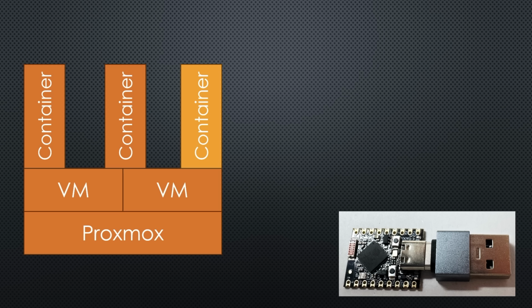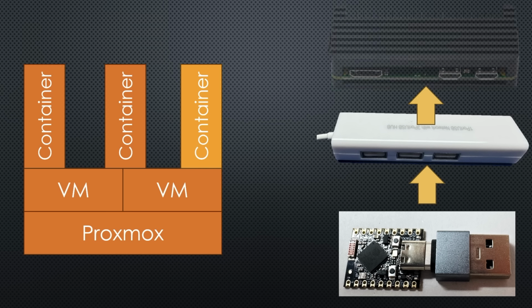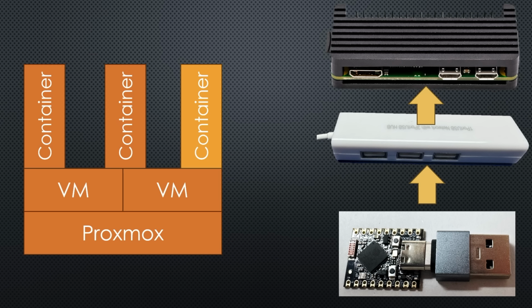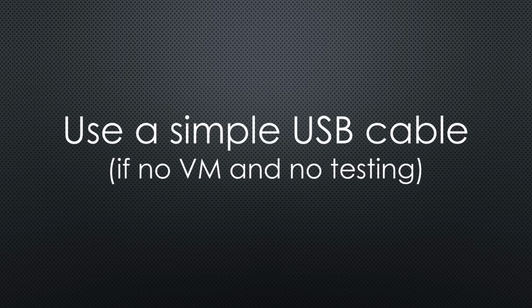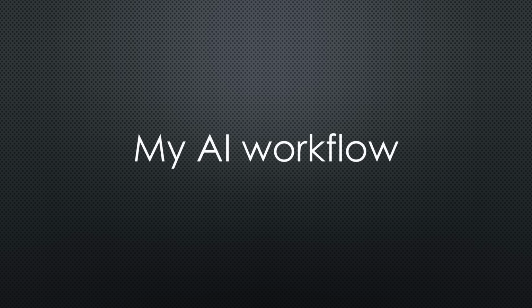My overall development setup looks like this. The ESP32 is connected via a USB hub to a Pi 0. The Raspberry is connected to the VM via an Ethernet cable. Like that, Wi-Fi can be used for testing. If your computer has a serial port and you do not need automated testing, you can simply connect the ESP32 directly to your computer.